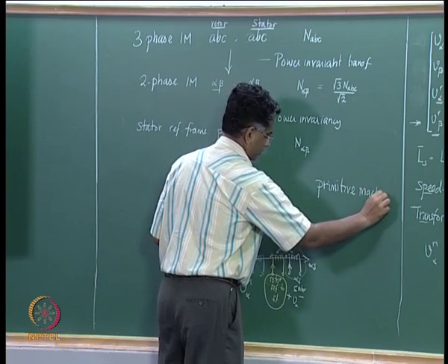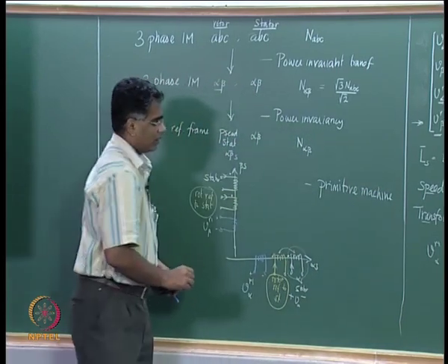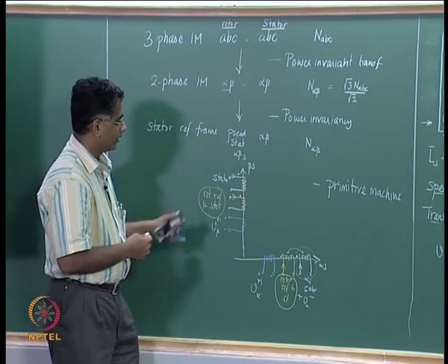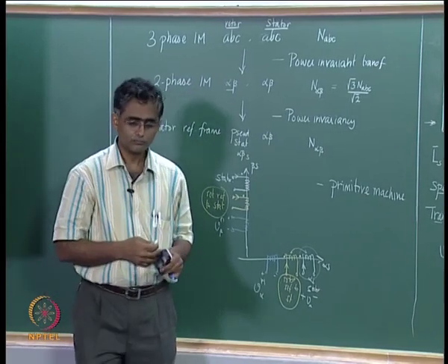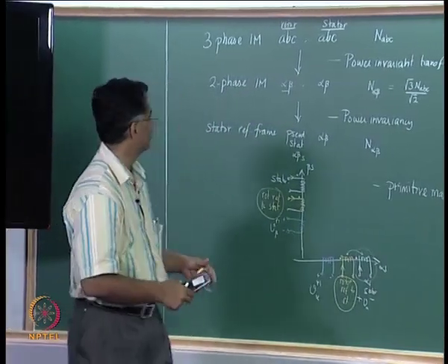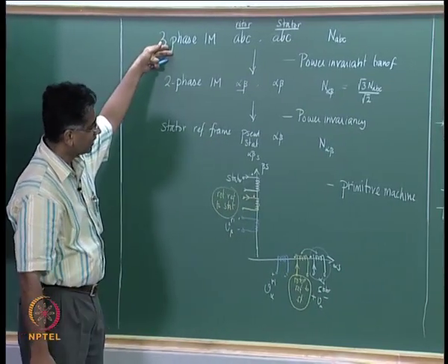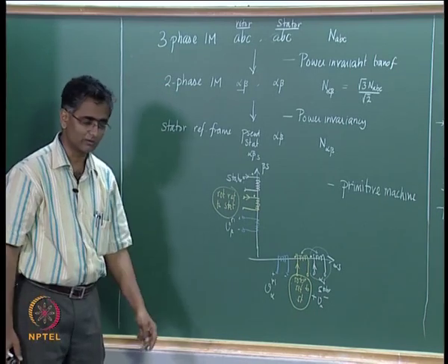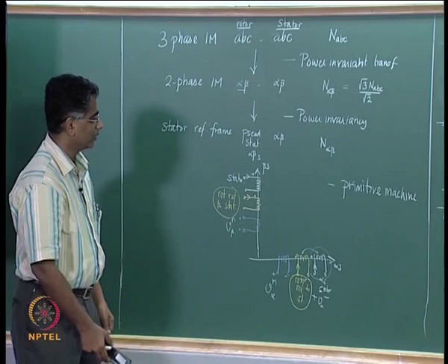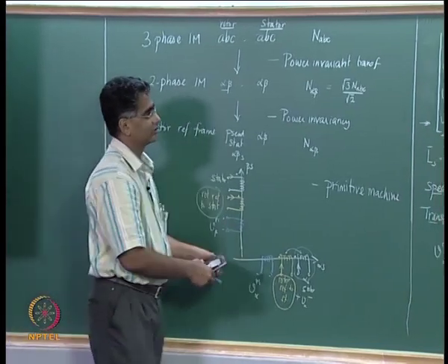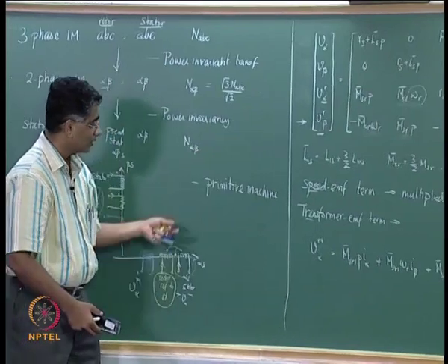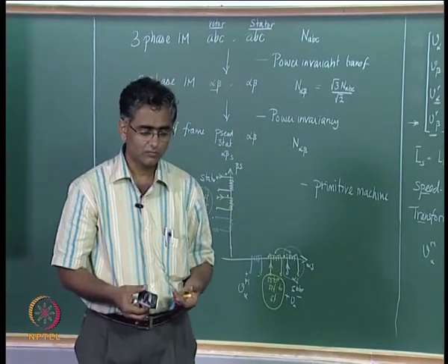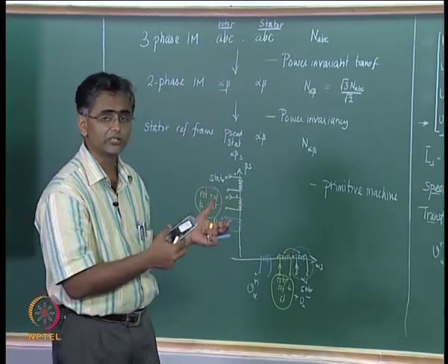electrical... Why is it now given a name like that? We have derived this machine description starting from an induction machine. We started from a 3-phase induction machine and then a 2-phase, and then we referred everything to stator. But as we go along, we will see that this machine description that we have derived can be used to describe any electrical machine that falls in the group of machines that we are looking at.